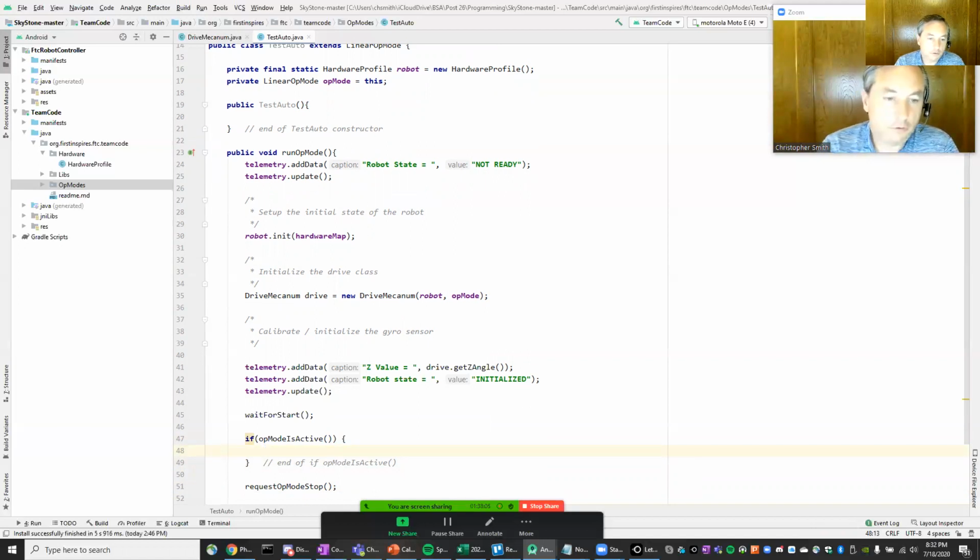So what we're going to do in order to call this is we're going to use our drive class that we put together. So we're going to say drive.robotCorrect, right? That was a method that we created. And now it wants to know what power. So let's not go too crazy with power. So 20% power or 0.2, heading. And we can test all sorts of directions here, but we can try 90 degrees because 90 degrees is kind of interesting. 0 degrees isn't particularly interesting, but you could do that. And then we're going to set the duration, and we might set the duration to 10 seconds, right? So it should be in seconds.